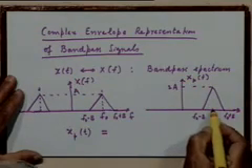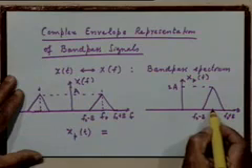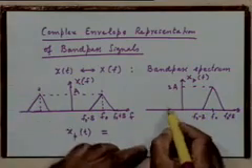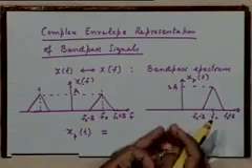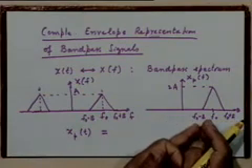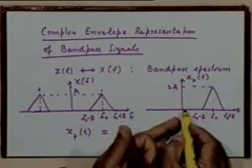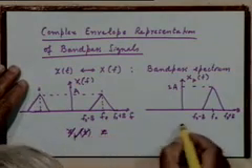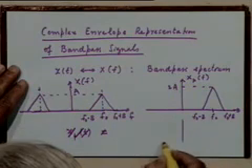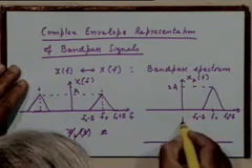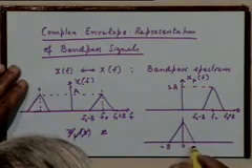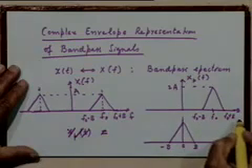Suppose we have chosen a particular bandpass center frequency f0, and I am shifting it. I am considering this signal as a frequency translated version of a low pass signal. The frequency translation is by an amount of f0. Right? So same shape, instead of centering it around f0, I will center it around 0. What I am saying is you can think of this as a translated spectrum where the original spectrum is like this, and the translation is by an amount f0.